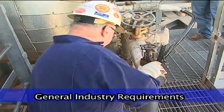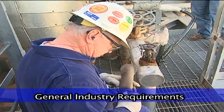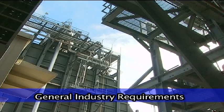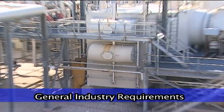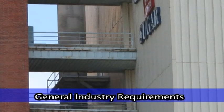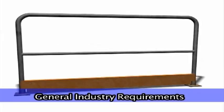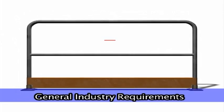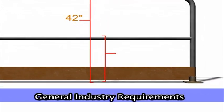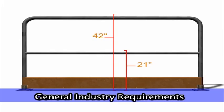Anytime an employee is working 4 feet above a lower level, fall protection must be provided. The 4-foot rule applies, but is not limited to open-sided floors or platforms, runways, wall openings. For the most part, fall protection can be provided by a standard railing consisting of a railing, a mid-rail, and a post. Height from the upper surface of the top rail to floor level should be 42 inches. The mid-rail height is 21 inches, and the ends of the rails should not overhang the terminal posts.